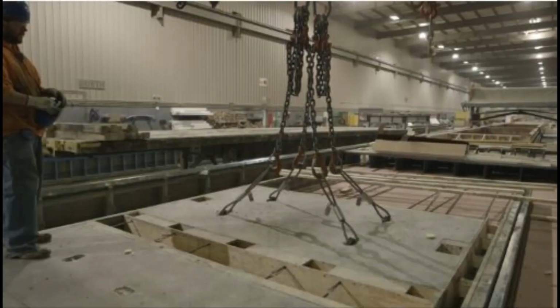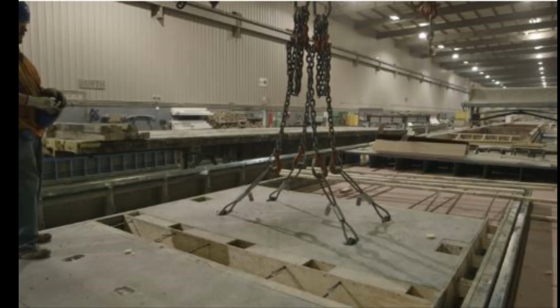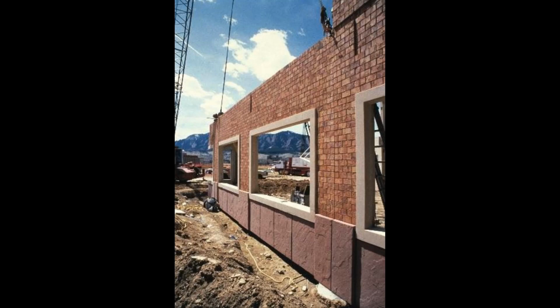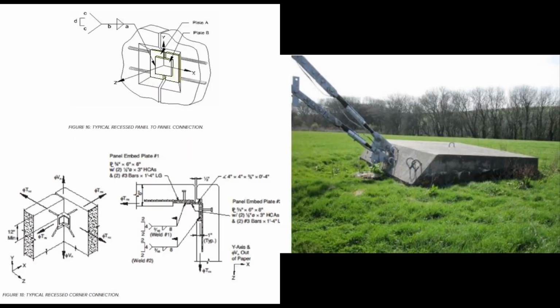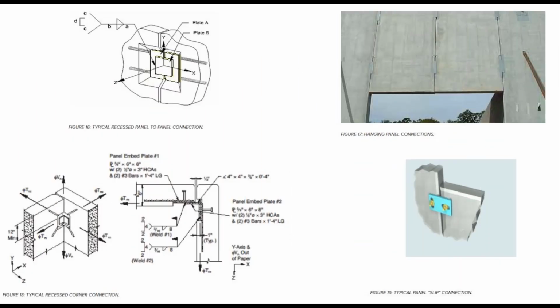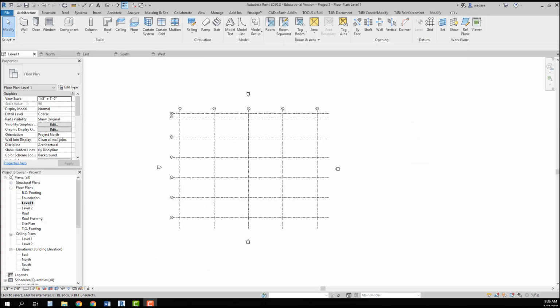There are many other elements that you have to take into consideration when using precast. You have to look at manufacturing tolerances, design responsibility, structural planning, handling loads, brace design, connection design, etc. That's a lot of information, but again, it's important to understand the differences in the types of panels that are available and all of the other elements that go into precast panels.